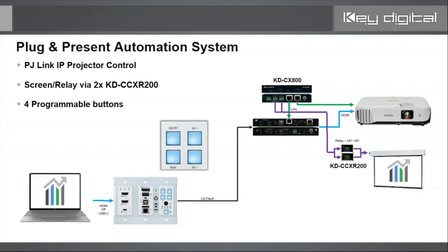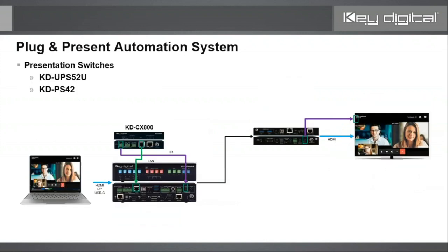We're also adding motorized screen control by adding two of our contact closures, model KD-CCXR200. That'll allow you to create a relay control. And those 4 buttons on the wall plate, KDX-4x1WUTX, can now be programmed to control any device that you'd like or send any command, so it's now going beyond just the CEC commands that are built in.